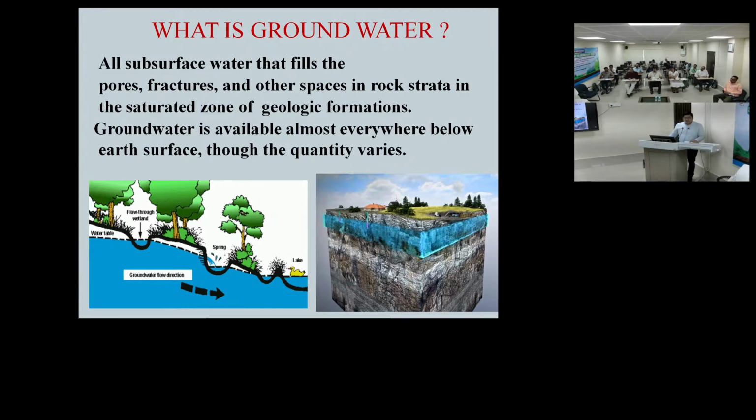Even in Guwahati, when you go for water wells, I can give an example. The latest example is the BSNL telephone exchange in Pan Bazar. We wanted a piezometer there, so we went down to 184 meters. Till 60 meters there was soil, what we call the weathered zone, because in hilly areas there are two things. The weathered zone is valley fill, because those hills have had deposition and weathering time and again, coming as a soil layer, forming a sedimentary layer.